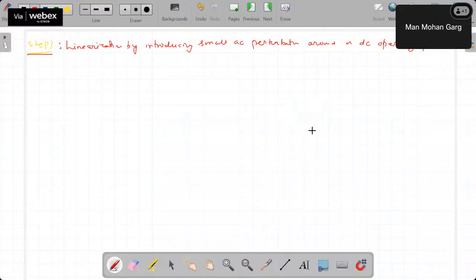So what is this? First, let us see why we are doing linearization. Let us say this is some system dynamics, and it is varying in this way. But most of the time, my system will be working around this value. Let's say my converter output should be 10 volt in general. Sometimes I may need 8, sometimes 12. But I cannot say that I have designed a converter for 10 volt and sometimes I need 100 volt from it. Never, right? Similarly, for input voltage, let's say nominal I have designed for 20 volt.